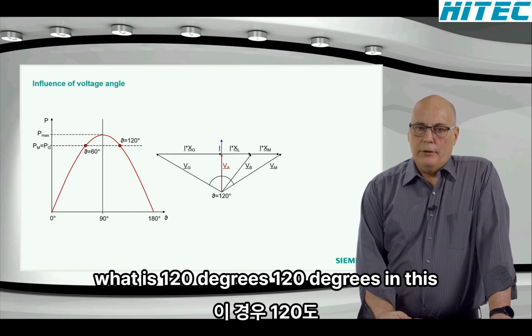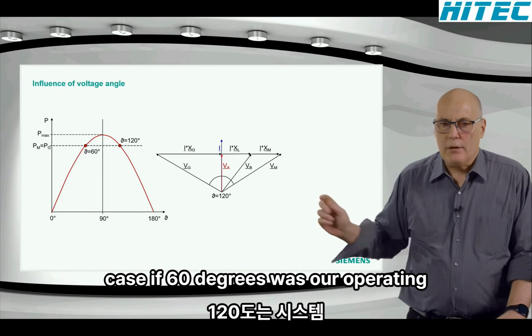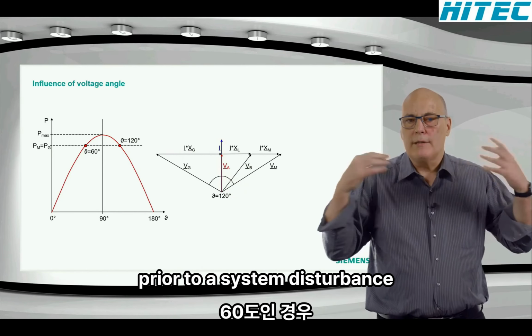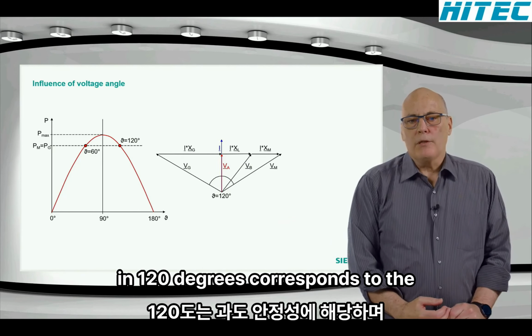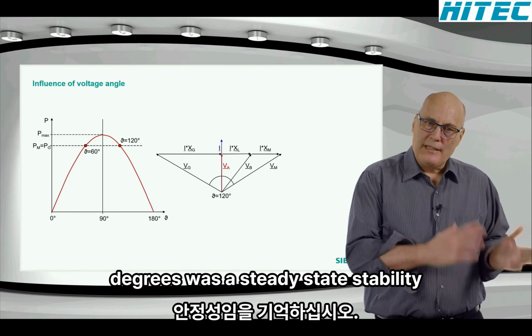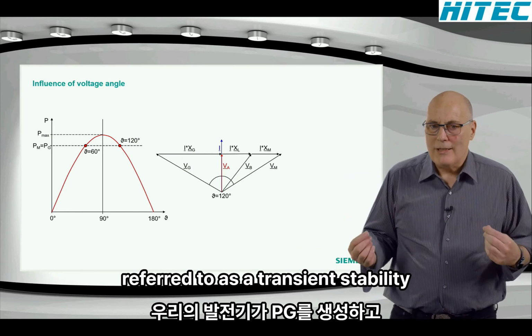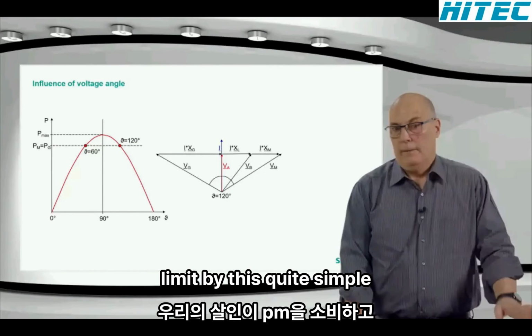What is 120 degrees? In this case, if 60 degrees was our operating point prior to a system disturbance, then 120 degrees corresponds to the transient stability limit. Remember, the 90 degrees was a steady state stability limit. 120 degrees would now be referred to as a transient stability limit. Why?